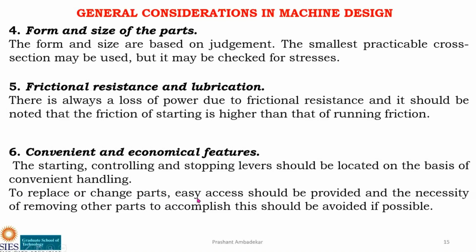Then to replace or change a part, easy access should be provided and the necessity of removing other parts to accomplish this should be avoided. I told you at the start of the earlier lecture that if you want to remove a particular nut, it should not happen that you are removing the entire assembly. So the parts should be assembled such that it is convenient to do the maintenance of that particular part. So these are convenient and economical features.